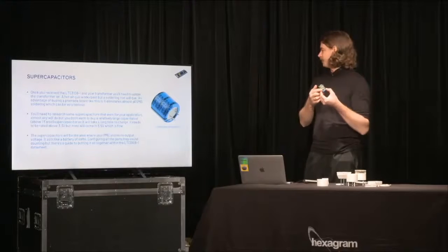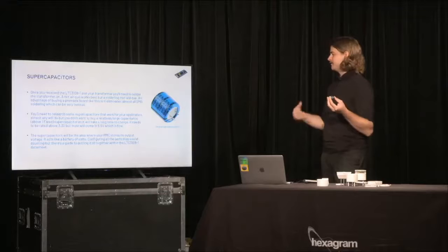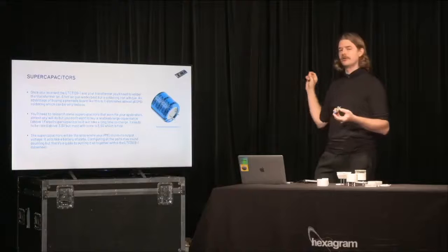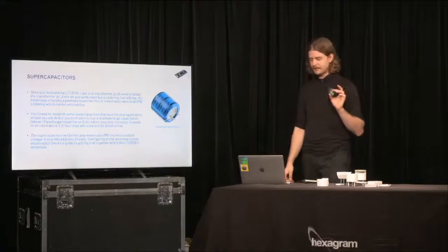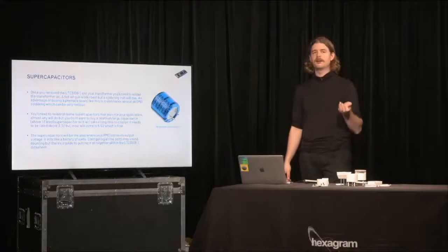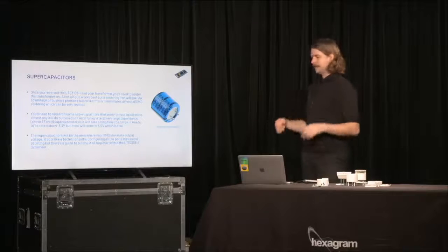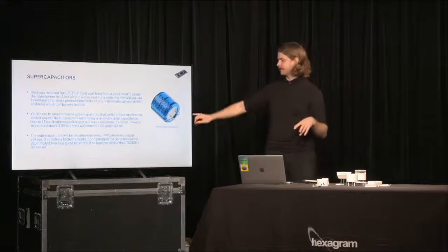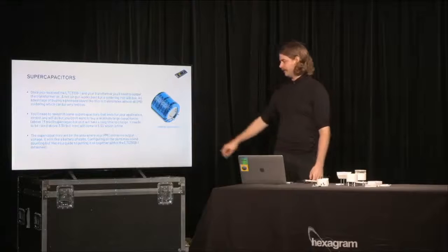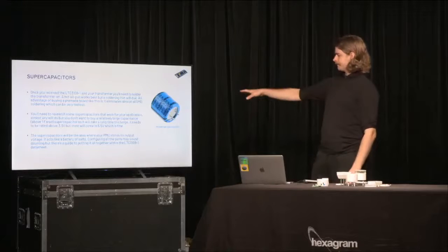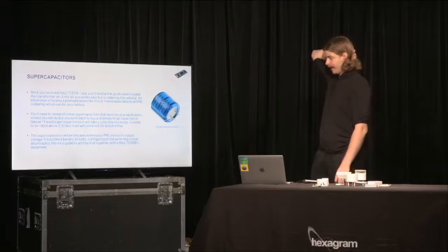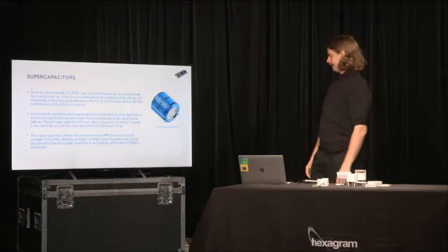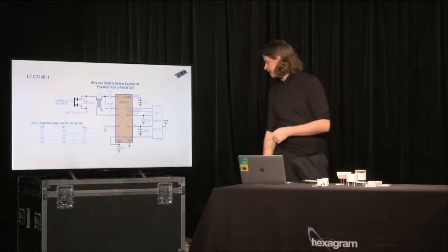These things are supercapacitors. They're kind of going to be the energy backup. So when you're harvesting energy, you have to dump it somewhere because you're not supplying the microcontroller with energy all the time. If you're stepping up like 1 millivolt to 3.3 volts, obviously it's not sustainable to just pull it all the time. You kind of have to slowly build it up in a battery and then discharge it. Or not a battery, sorry, a supercapacitor. You can use batteries, but these are easier. Basically they're all going to be 5.5 volts. That works, it's okay, as long as your voltage isn't above the rated one. And I'm going to show you exactly how to hook it up, that you can come back to this.